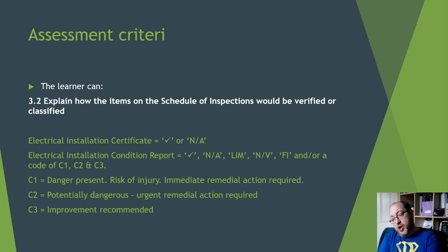because they want to. But if you go to the section on testing in part 3, which is Guidance Notes 3, page 83, it tells you with the tests to be made, for example, ring circuit continuity. Where there are records of previous tests, this test may not be necessary unless there may have been changes made to the ring final. So again, it is up to the inspector to determine the state of the existing system, any recent work, any modifications.